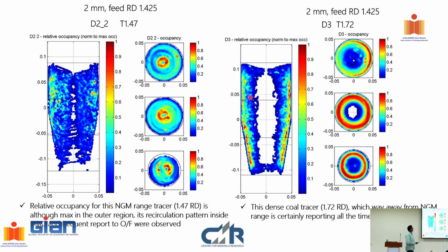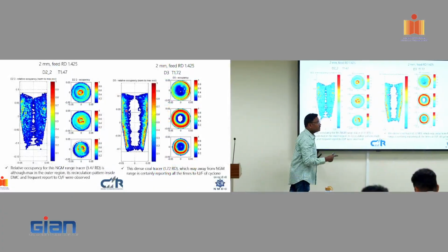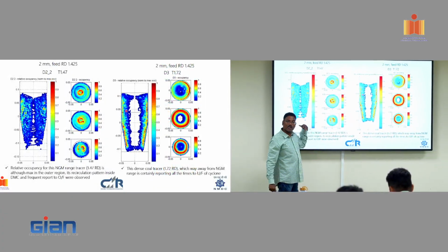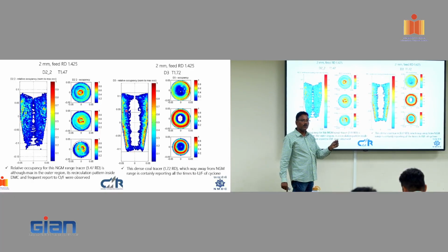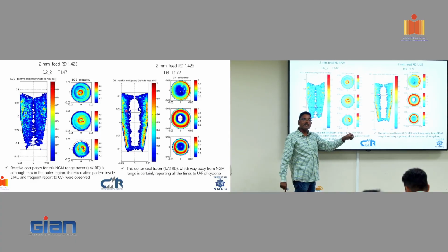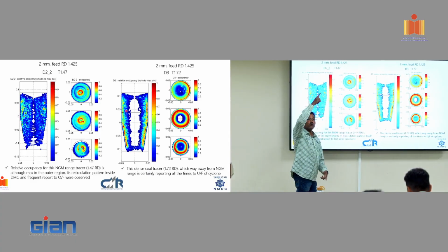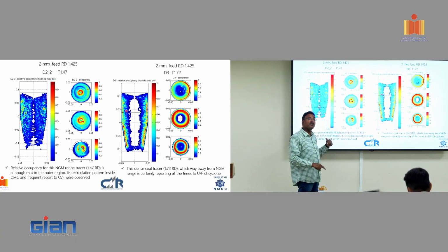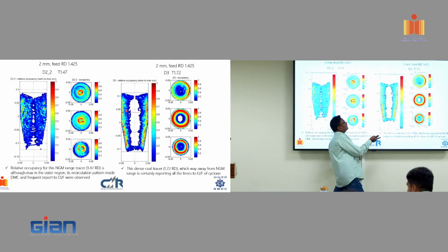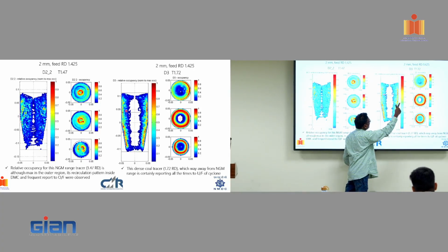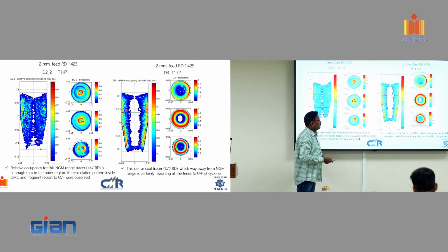You can see very much. This is for the particle which has a density closer to the separation density, and you can see circulations, and we can estimate the residence time is quite significantly high. Whereas for the remaining density particles, in less than 2 or 3 seconds the particle comes out of the cyclone and goes back. These particles take a longer time to come out to the product. And higher density particles, you can see, are quite far away, and they are also following the path.